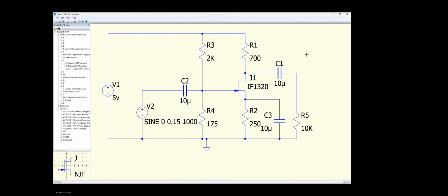However, let's add some reference names so we can do some calculations. Right-click on the net between C1 and R5 to bring up a menu and select Label with a left click. A small red dot with the text will attach to the wire. Double left-click the red text. Use the backspace key to empty the net name and then type VO for voltage out, then hit enter.